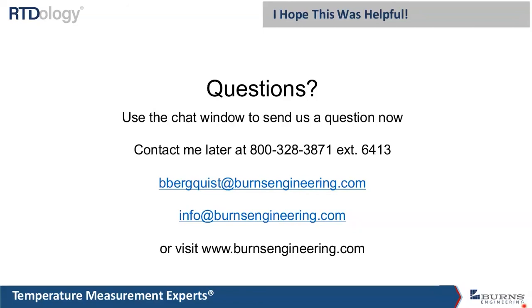Here's a question about going back to connection heads. Do you see those more in any particular applications, or are there common points in a process where the connection heads are necessary? I always like to use a connection head just because it makes maintaining the probe a lot easier than having a big long cable attached directly to the probe. It also helps protect the back end of the probe from moisture or wash down.